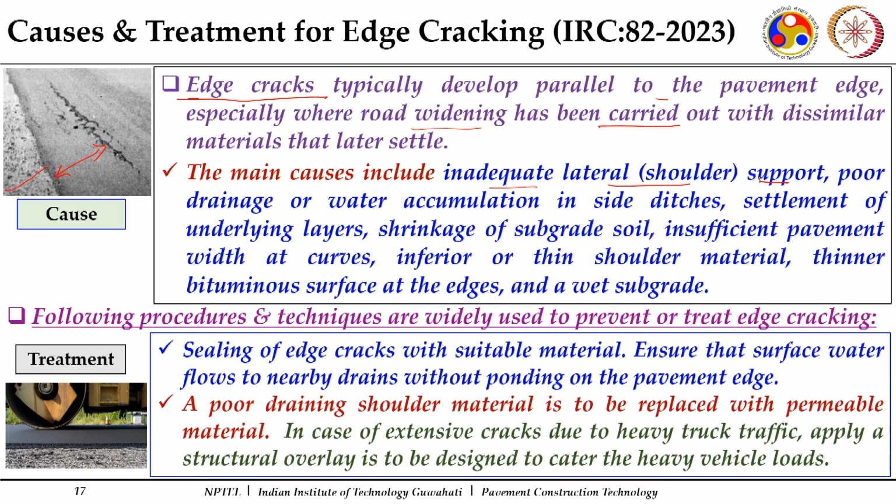If the edges are not supported by your shoulders, or there is poor drainage or water accumulation on the sides, the water will stand on the pavement edges, go inside the pavement layers and weaken those layers. So, specifically the edges, where high stresses are already coming up, will experience more deflections, and these cracks are going to get initiated.